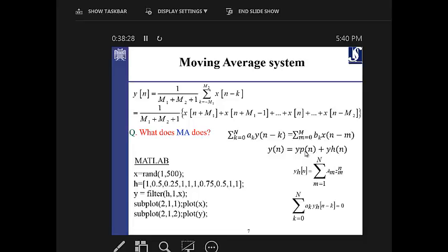You can have a Gaussian, but then it's not called the moving average. What you say is windowing. You can have different types of windows. For example, in the short time Fourier transform, you use the Hamming window or Hanning window or Kaiser window or whatever. But simply taking the rectangular one is called moving average. Use this example and you will understand exactly what's happening. You can change the values, you can change the filter. Here I manipulated the coefficients. So you can fix these values all to 1, then it's a standard moving average, and if you change these values, it's a low pass filter.